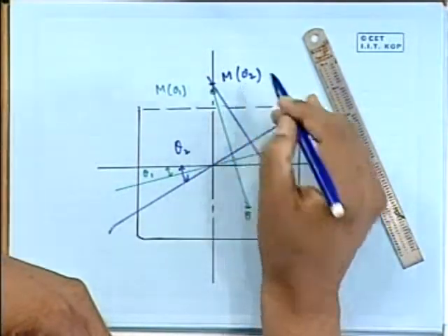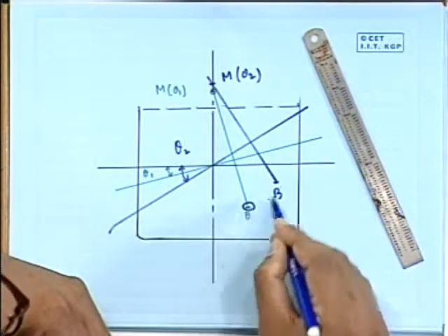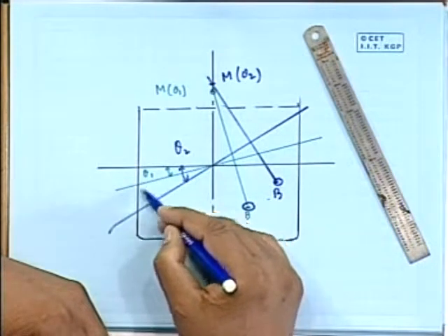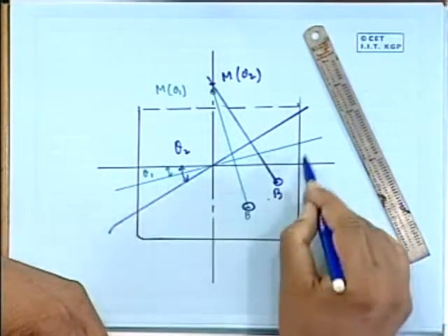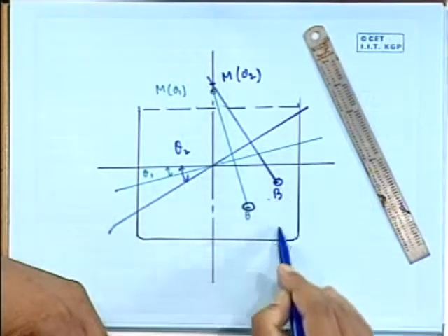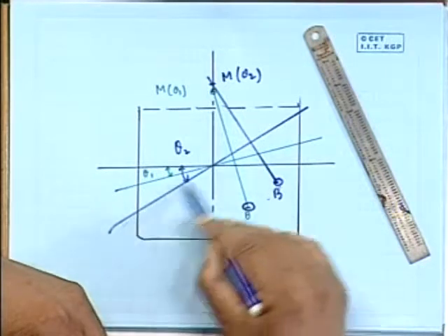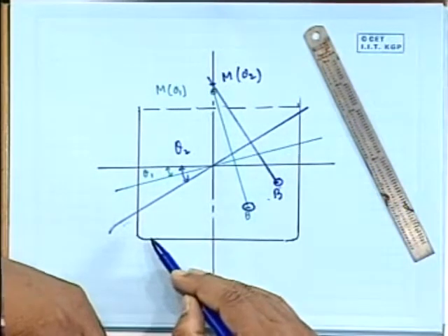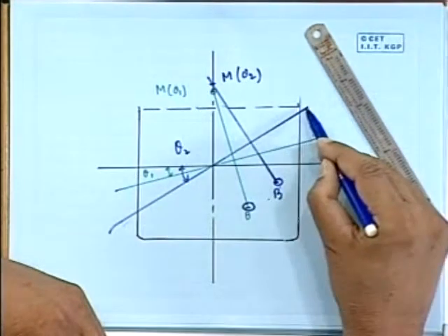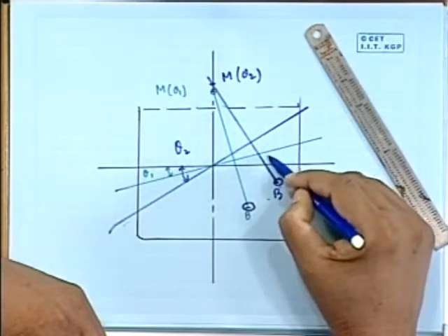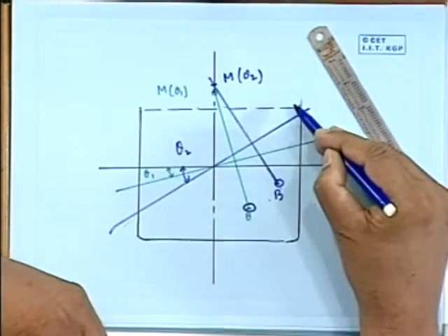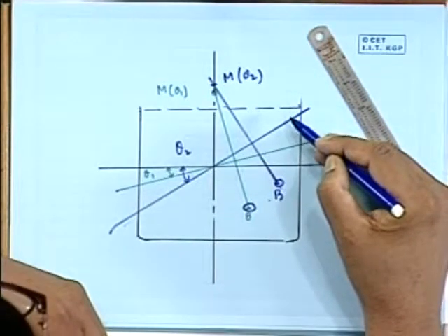because look at this point B, it obviously depends on the underwater geometry. What is B? B is the centroid of the underwater hull. This green B is the centroid of this green line, and this blue one is the centroid of this blue line. Obviously, they will depend on the angle of inclination, because the blue line is inclined by some angle theta. So the centroid location will depend on the amount by which you inclined.